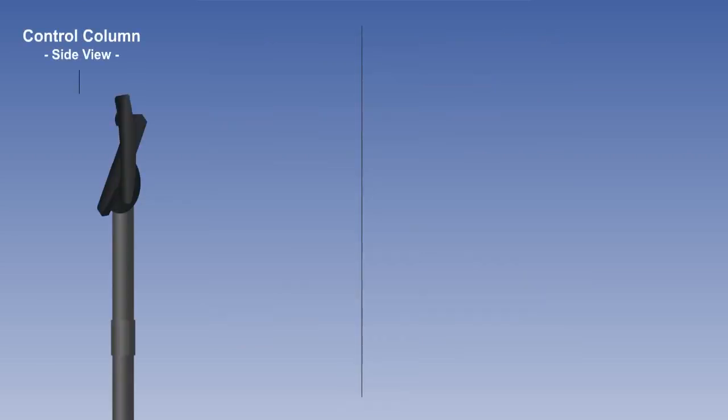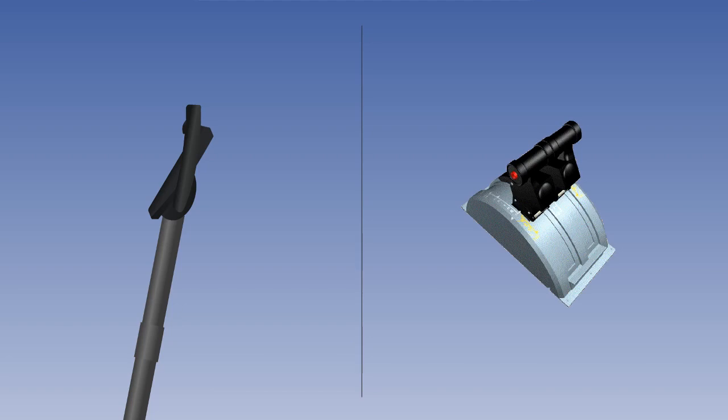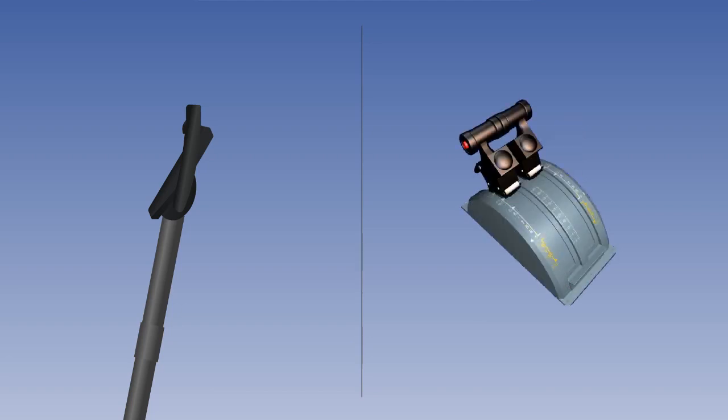There is also a test facility, which can only be used on the ground to test the system. A stall protection system differs from the stall warning system only in that it is triggered at a later stage than the stall warning, and it has different outputs. In a traditional aeroplane, we have the stick push, whereas in more modern aeroplanes, we have an output to the auto throttles, which move them to take-off go-around thrust.